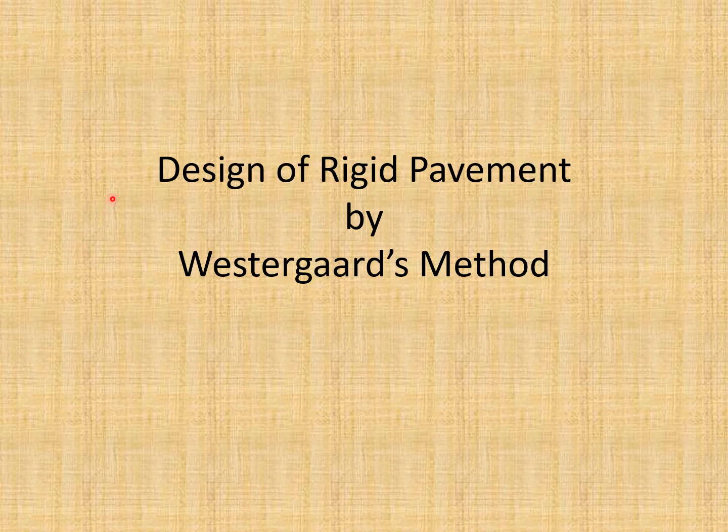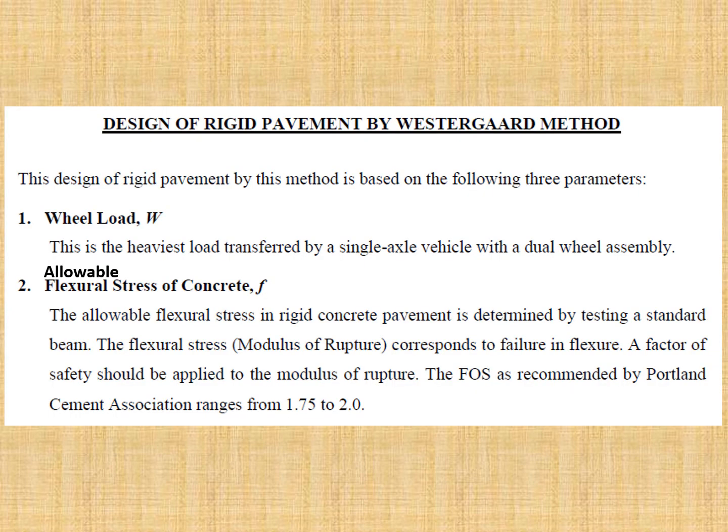Okay, now we have reached the design of rigid pavement by Westergaard's method. The design of rigid pavement by this method is based on the following 3 parameters. Number 1, wheel load, W. This is the heaviest load transferred by a single axle vehicle with a dual wheel assembly.